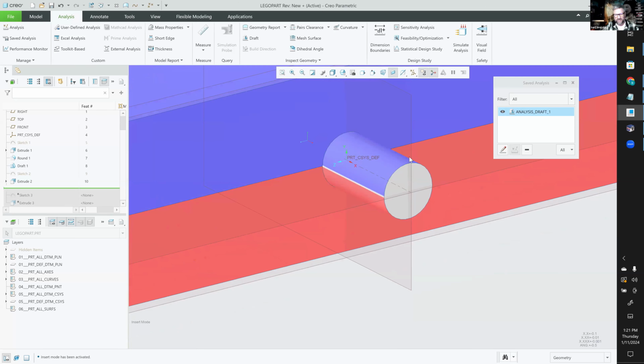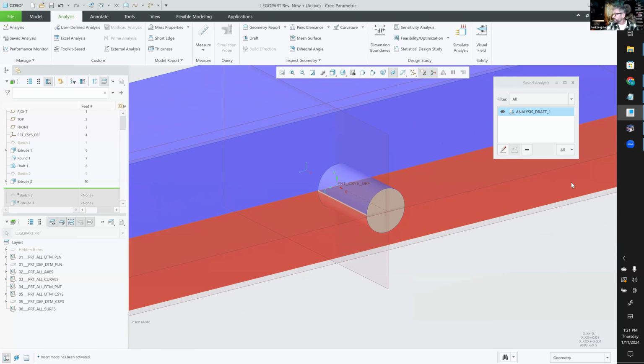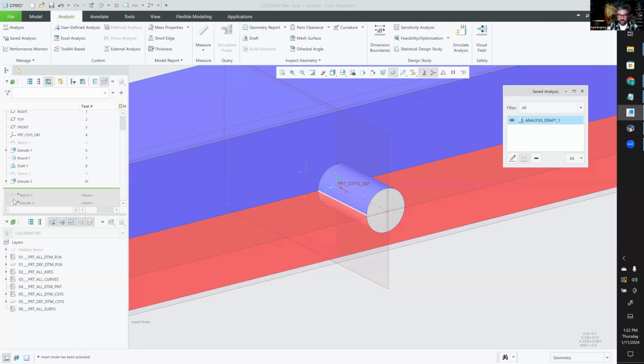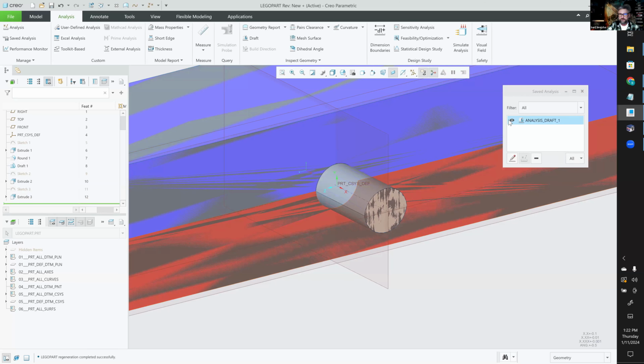So the typical Lego block is an ABS, but they'll use a wide variety of parts, different types of plastics as well. And of course there's no texture on a Lego part, or little texture, so they can get away with less draft.